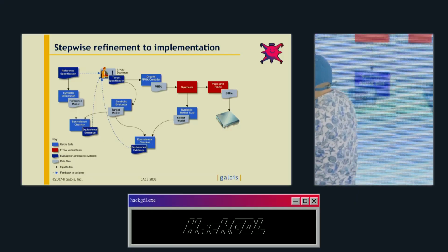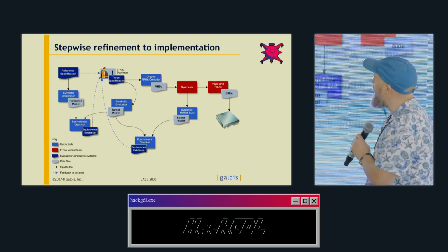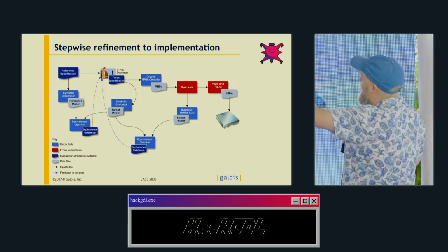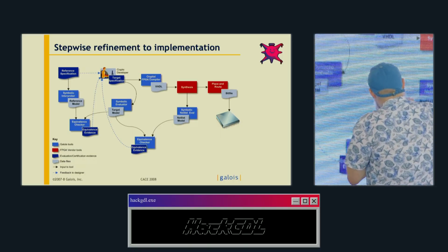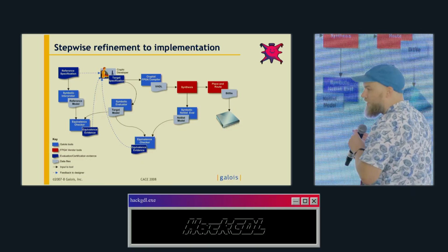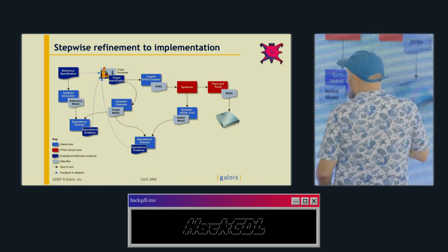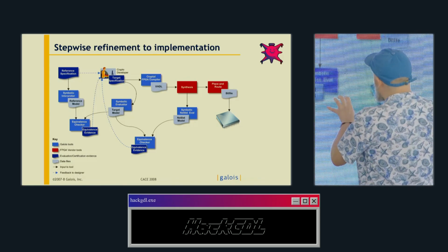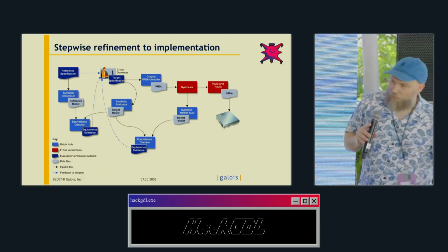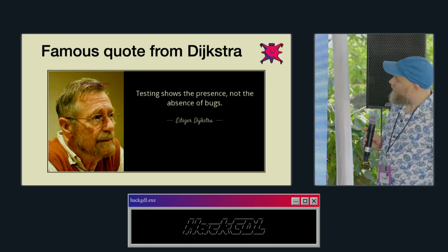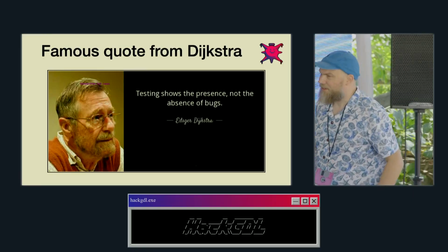So first of all, you want to know that your reference specification and target specification are correct. So the high-level spec and the more concrete spec, these two you want to prove to be equivalent. But last, you also want to prove that your netlist, which is just another fancy term for circuit, is also still correct with regards to your target specification. And the Cryptol tool uses these things called SAT and SMT solvers underneath to prove this for you. And the thing is, without verification, the only thing you can do is testing.